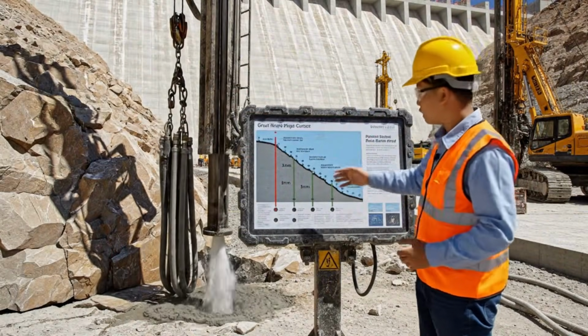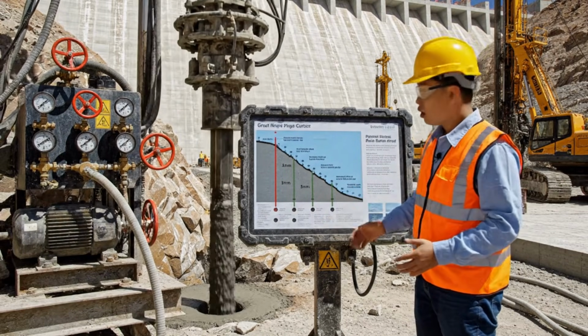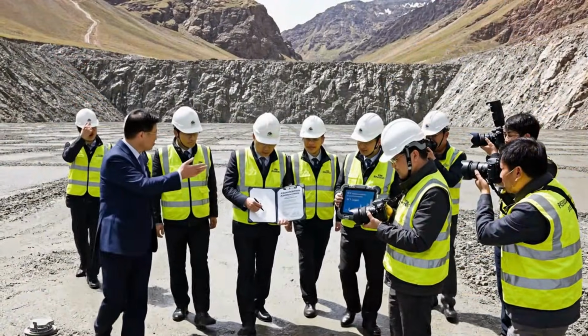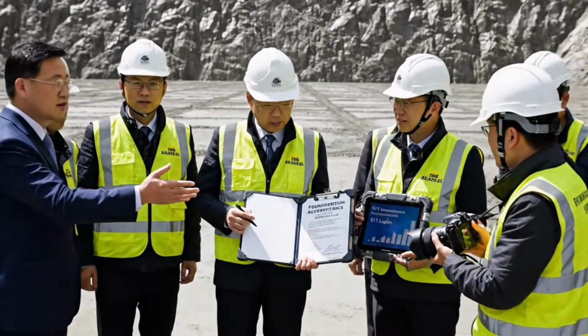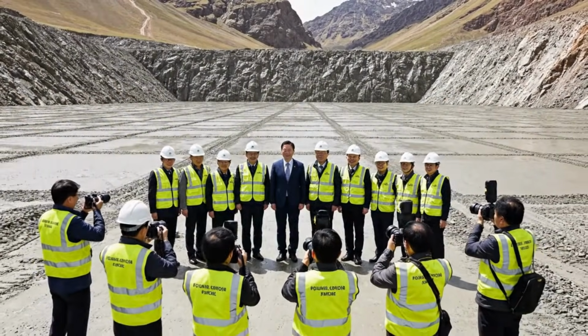This curtain grouting creates a watertight barrier 80 meters deep and 800 meters wide. We use multi-stage injection to penetrate the bedrock. So the Lugeon tests confirm the permeability. It meets the standard. Absolutely, the foundation is officially accepted.